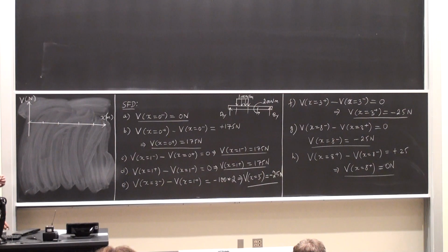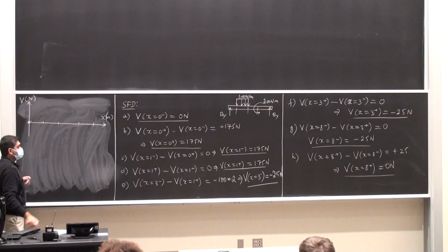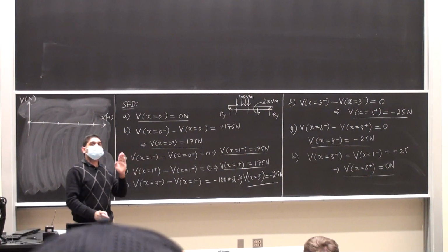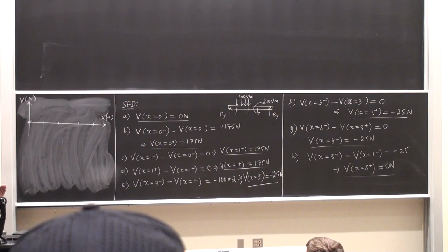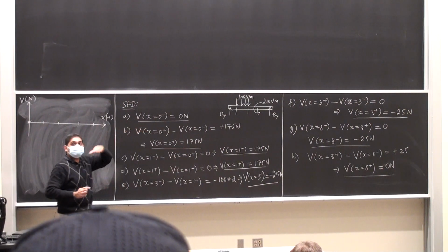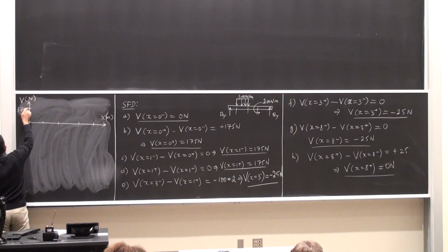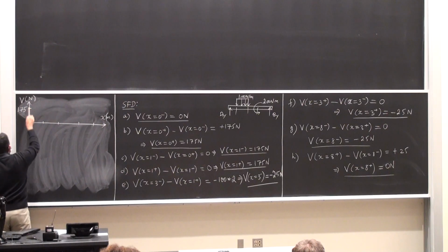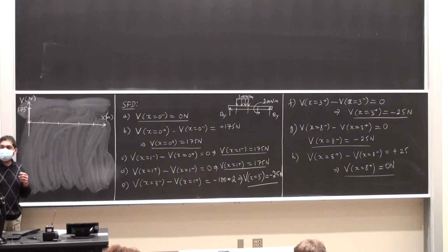Okay. At 0 I start at 0. That is 0 minus. Between 0 minus and 0 plus there is not a whole lot of space. So when I am drawing 0 plus, I am directly shooting from 0 newtons to 175 newtons straight up. Okay, it is positive 175, so I'm going to go up on the shear force diagram. 175, so this is a line that I join. So far so good, everybody?